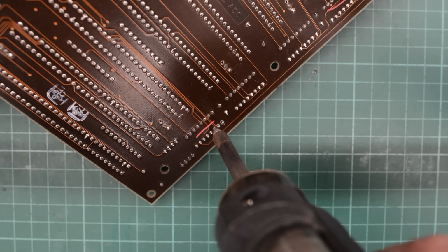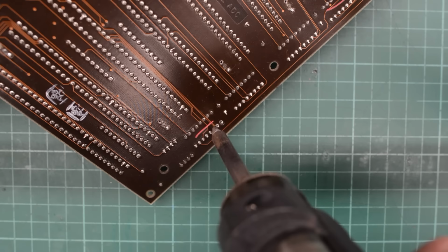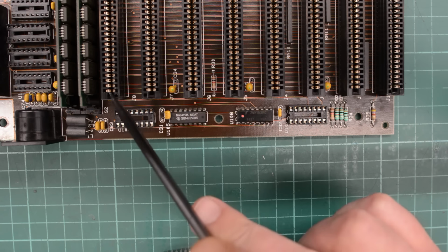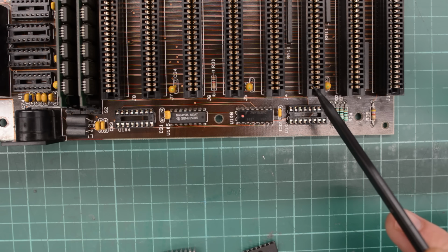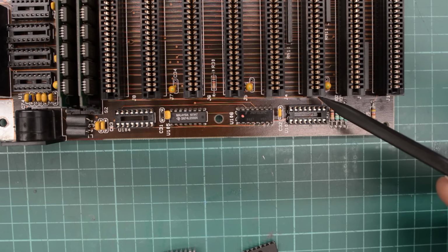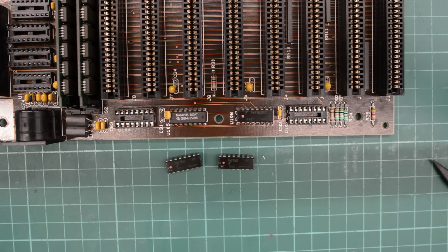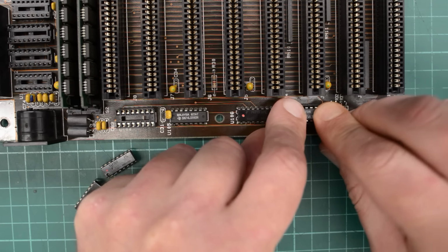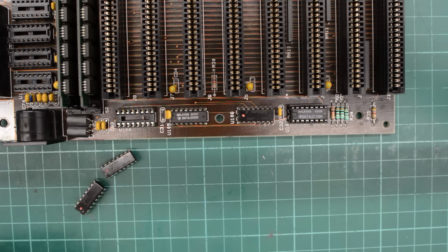So I'll go ahead and put these two chips in sockets. Okay, same procedure as with LS125, with one difference: these are very close to the ISA slots, so I had to be very careful not to melt these slots when using the rework station. I couldn't find any 74F158s, but I found one LS158, so hopefully it's good enough. This is a leftover, by the way, from the 640K hack in the 5155.